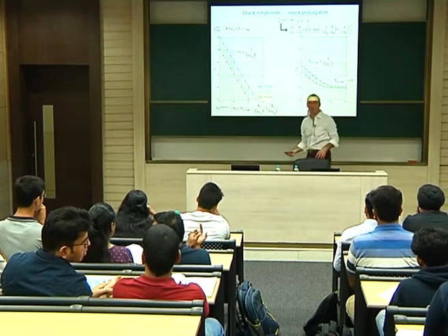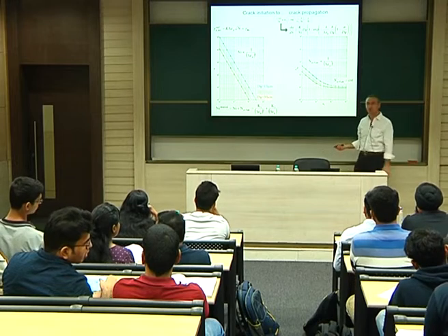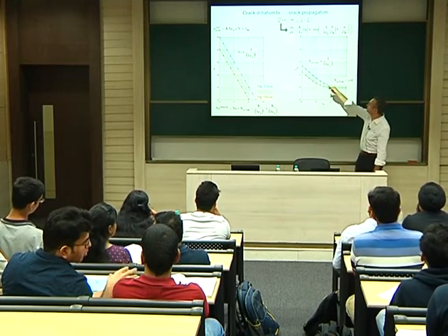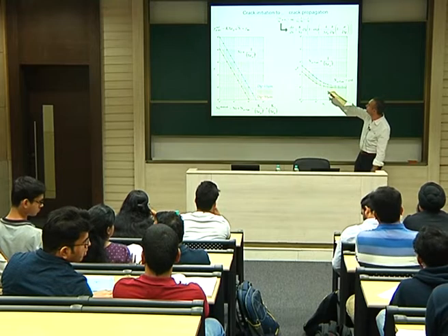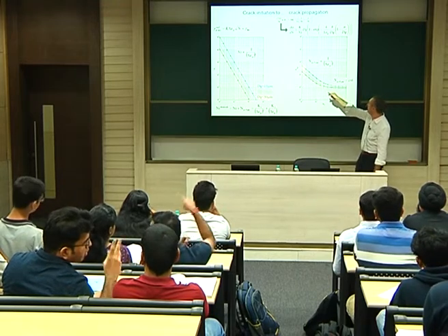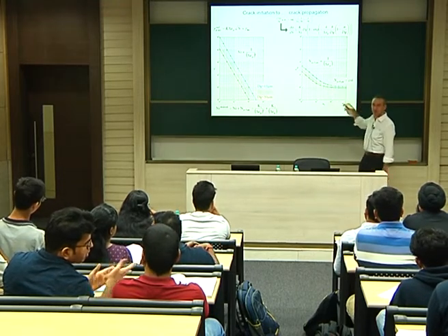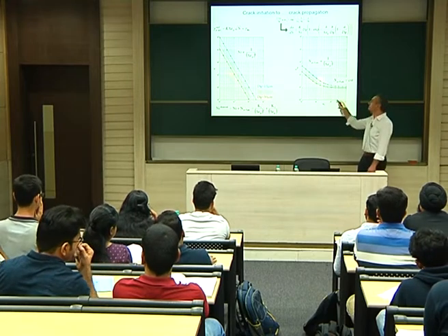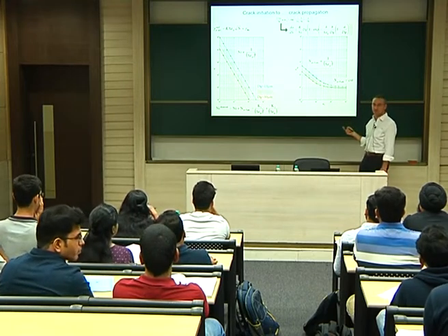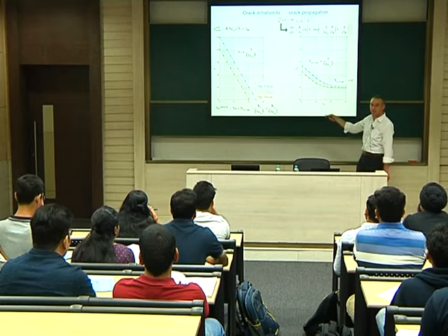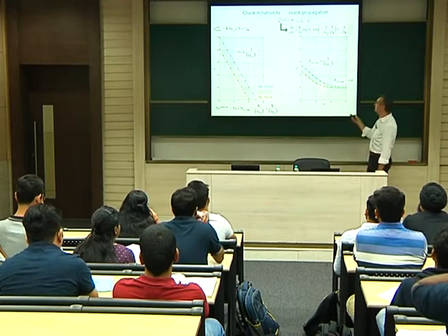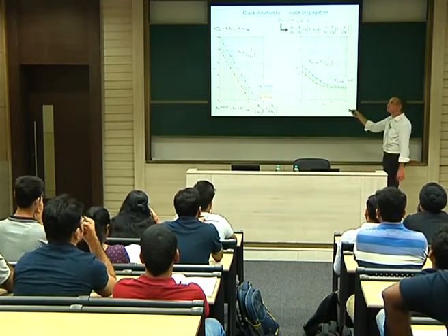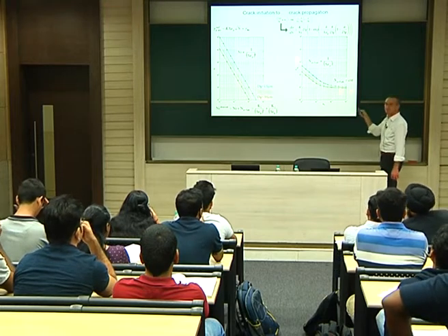Just to show you that in literature, many times you have this kind of curve, which is first a square root dependence. So if you plot it here, it will be somewhere down there, and then you have something which is like that when you have your crack. So this transforms into that from the PSB to the crack. Okay, that's the idea. So this is not for the crack. This is for the persistent slip band itself. For the crack, it's no more depending on the square root. It's like that. It's the exponential term. So there is something like that.